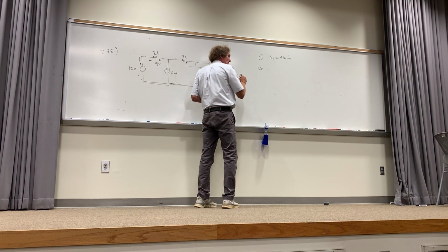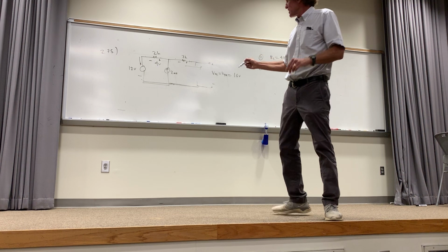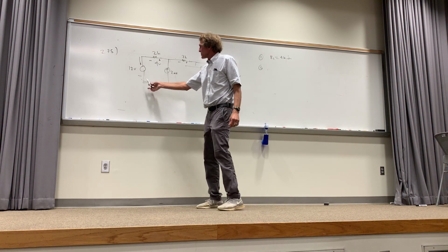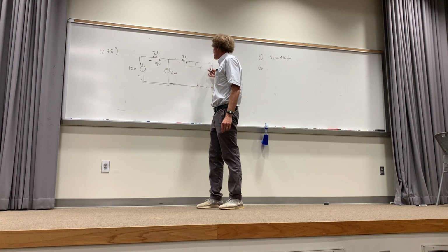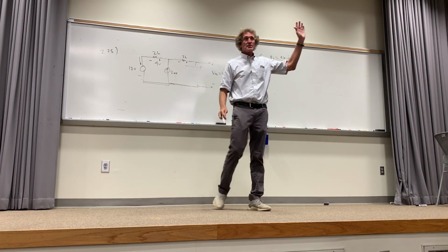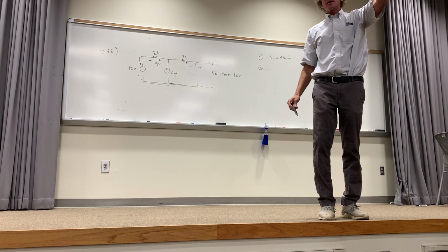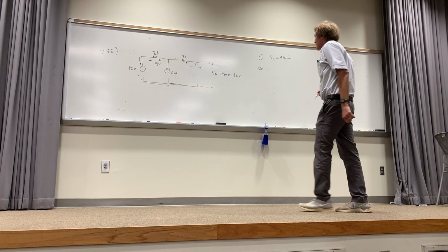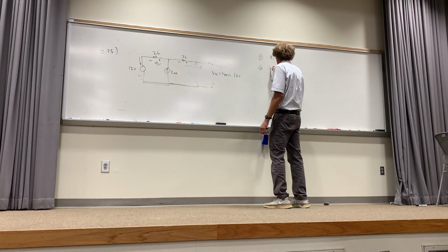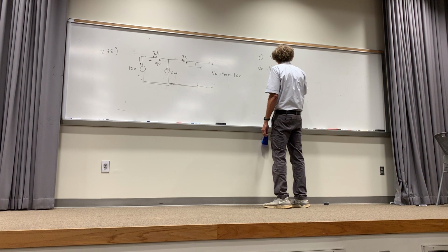Does everybody see that? I'm adding the voltages in series, right? Starting at the negative terminal here. I see this is an increase of 12, this is an increase of 4, that's a total of 16. Nothing there, so it's 16 volts. How many see this? All right, are you with me? Can you guys see it back there okay? All right. Now, so I got V open circuit, or V Thevenin, equal to 16 volts.